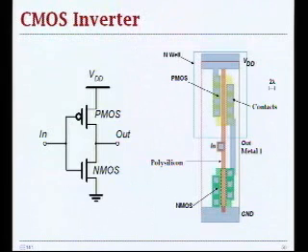This is a layout of a CMOS inverter. This is what you're going to do in the lab. In this N-well process, you put an N-well for the PMOS, then you put this diffusion region, then you have a lot of contacts for your well, and this is your drain side over here. Then you have NMOS in a similar way down here. You have well contacts, you have your drain, and then you have a gate polysilicon running on top of both devices, and then you have a common drain that's your output of the circuit, in metal 1.